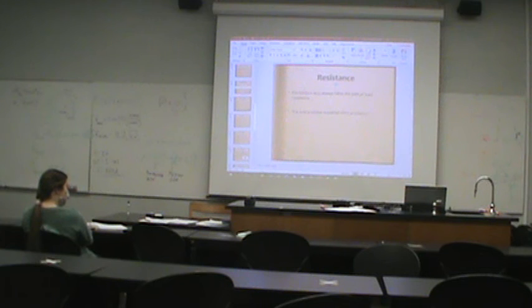So the professional advice for if you're in a car that has been struck by lightning or there's a power cable touching it is to stay in the car until someone arrives and you know for certain that the car is discharged. If you have to get out because it's a storm and something bad is about to happen to it, you want to touch only the plastic inside of the car. You want to open the door fully and then jump out of the car. You want to jump and be in midair, no part of you touching the car, and then both your feet land on the ground at the same time without touching the car.